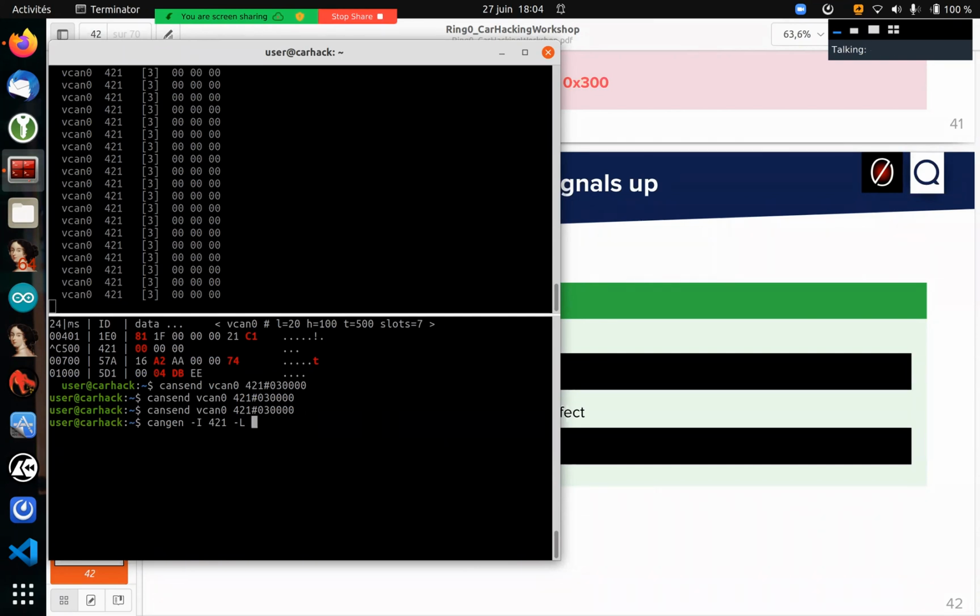No. Each CAN frame is manufacturer specific. If you are lucky, because when a tier one manufacturer works with a carmaker to design a car, they want to keep the stuff to an ECU. Let me rephrase. For a specific manufacturer, the same kind of ECU can be found in different car models, and they will have their own arbitration ID database.